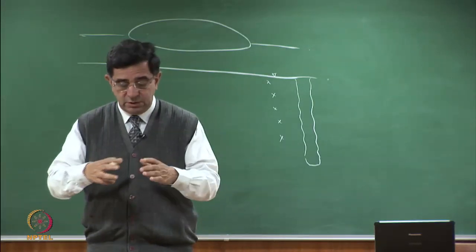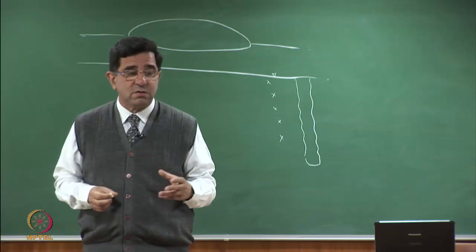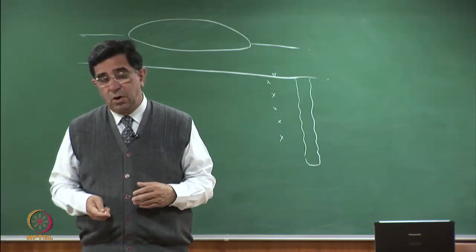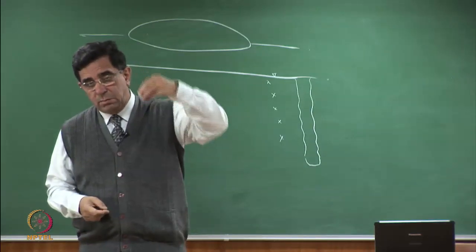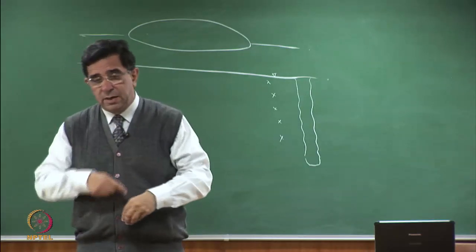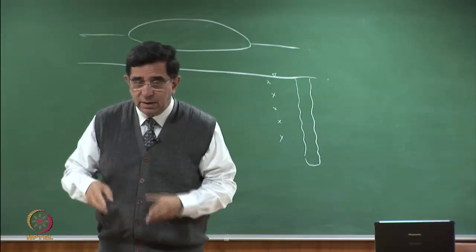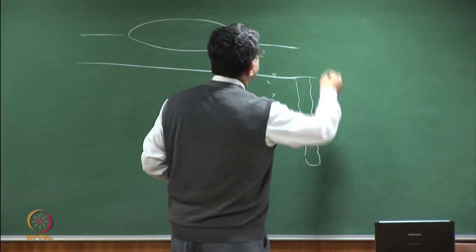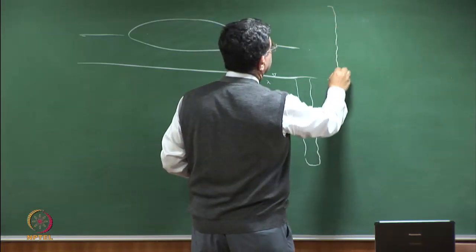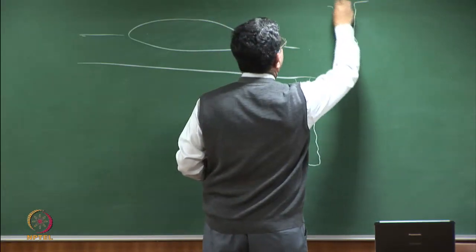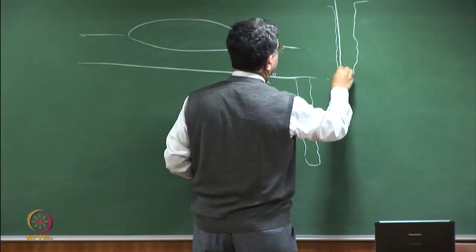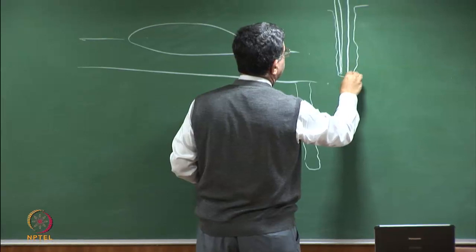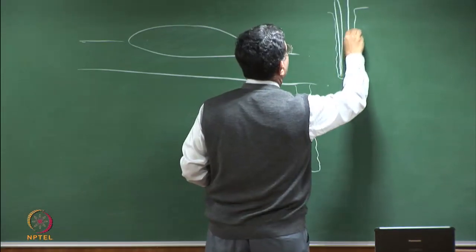Suppose I am making a 6-inch or an 8-inch diameter well. What is the drill tool that I will use? I normally use a casing with bentonite slurry being pumped into it, and I keep on rotating the casing, and the bentonite slurry comes from outside. An exaggerated view of the casing and a drill bit at the bottom.